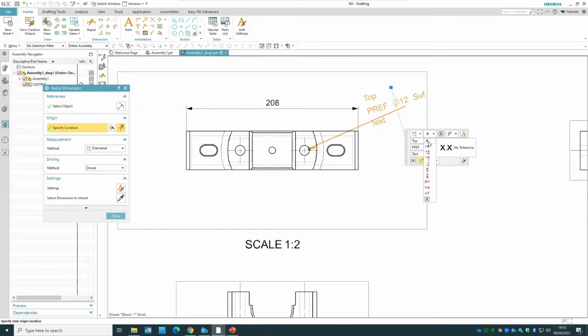If you want to have the tolerance, you can put the plus and minus here, and then you would be able to put the tolerance there. You can see right now it's 0.100, so it's 0.1, and then you will decide how many numbers you want to have. Let's say decimals. If I change these, you will see the decimals would then change.